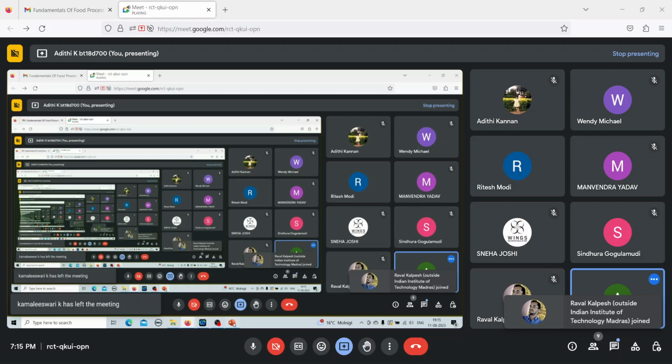So here I'm again substituting. Let's say I have the F value at 121 degrees Celsius, which is 8 minutes. I have the temperature 121 degrees Celsius and the other temperature T2 as 115 degrees Celsius. From there, I'll calculate what is F2.